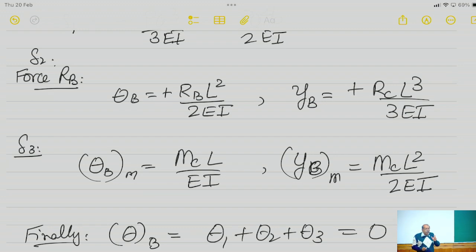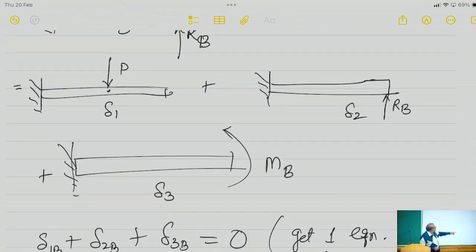See, here the tricky part was going from C to B when the point force was acting. What you have to realize there was the moment is 0, therefore the deflection takes a parabola and then it becomes a straight line. Delta 1 at C is not equal to delta 1 at B. You have to multiply it by that slope and by that length. Okay. So that's it. Are there any questions?